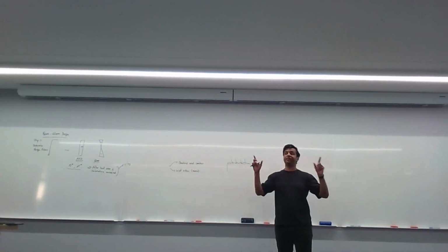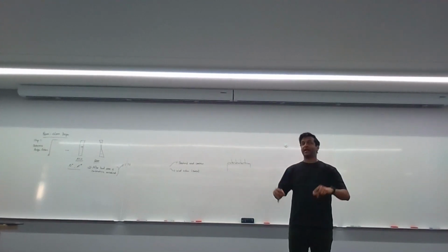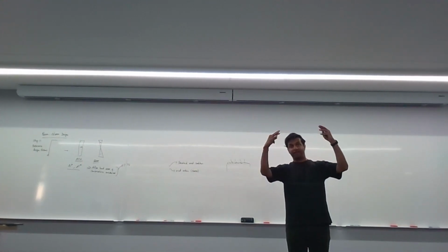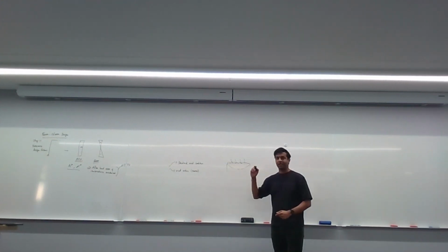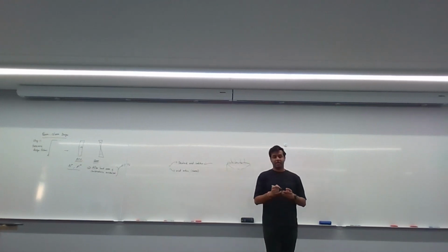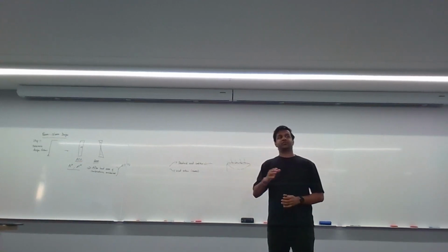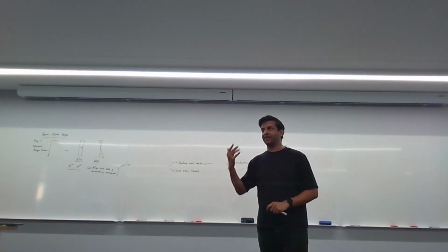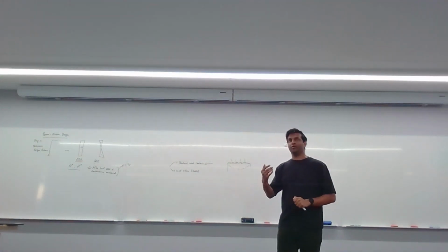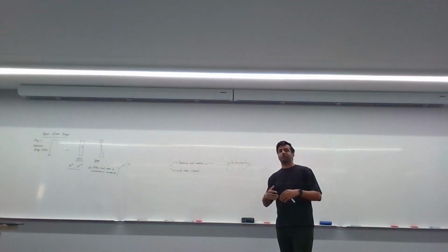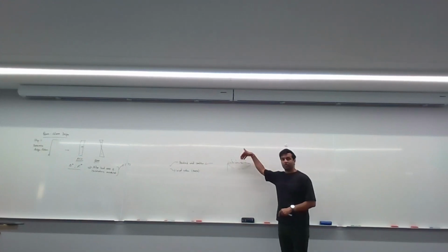So what is the worst effect? The most adverse effect is if your gravity loads and the wind and the live load, everything is pointing in the same direction. That'll give you the most adverse effect for that, right? So that is this case, okay? Now, when do you know if it's a standard condition or if it's a reversal condition? A standard condition is where your dead load G is higher than 1, the factor for your dead load. So for example, if your dead load factor is 1.2, something like that, that is because they're aggravating what the dead load is.